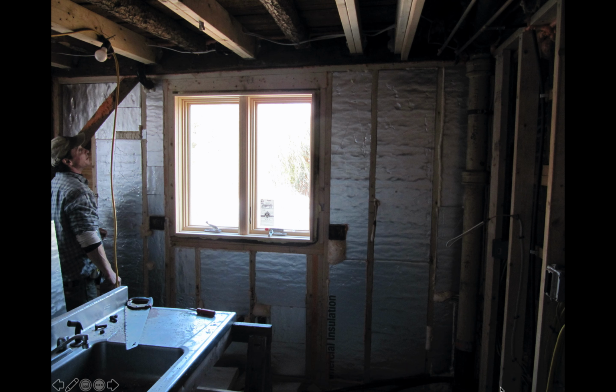Here you'll see an unusual use of board insulation. And the reason I'm showing this is to show that there's a lot of different insulation materials, and you choose them for different reasons. And typically one wouldn't do this thing, and I'll explain why in the class. But in this particular case, I was limited on the outside, and so I had to build toward the inside and maximize the R value, or the resistance to heat flow. And so this more expensive board insulation was useful just on this one wall.